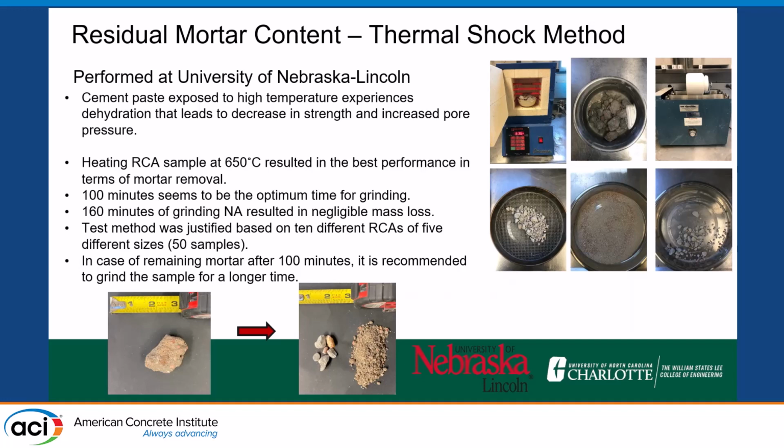And so with this particular test method, if you expose wet concrete to high temperature, it eventually experiences dehydration and leads to a decrease in strength, and eventually, as shown in those 2 pictures below, you break off all the mortar and you're left with the base aggregates, and you can basically do a weight change to see what your residual mortar content is.